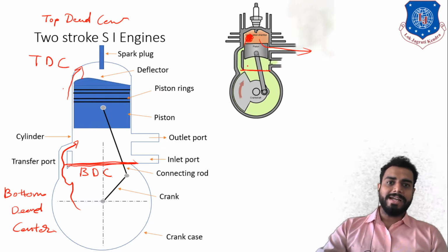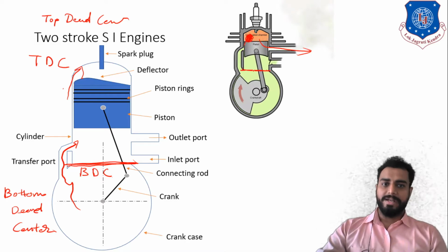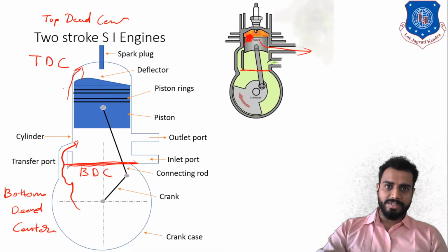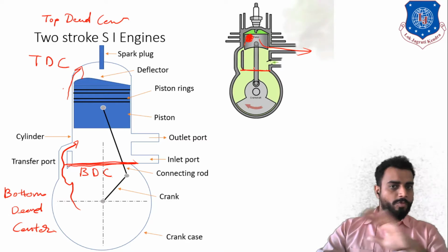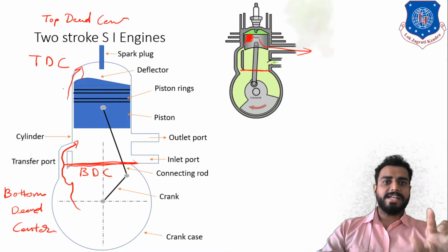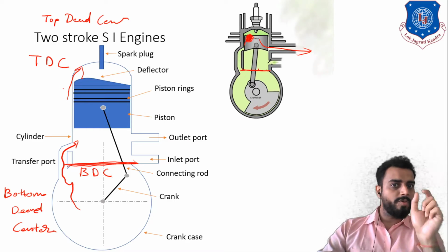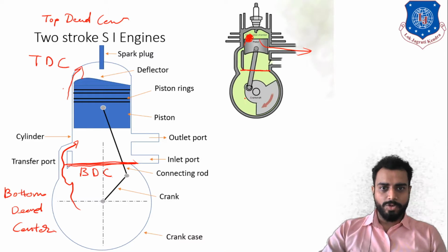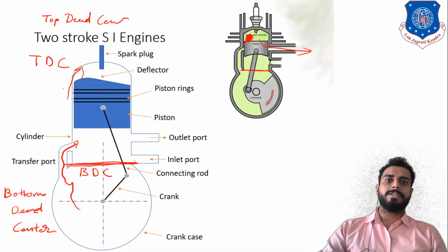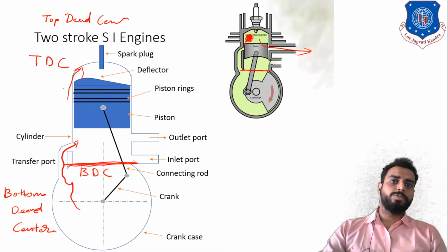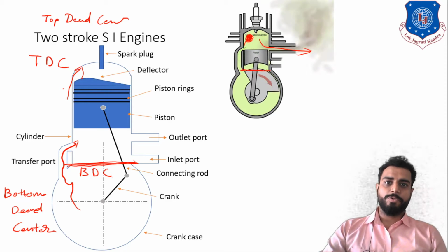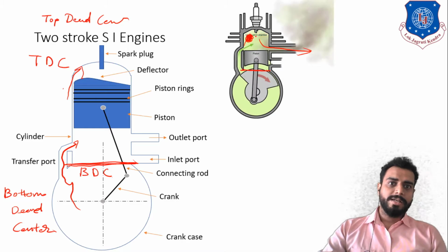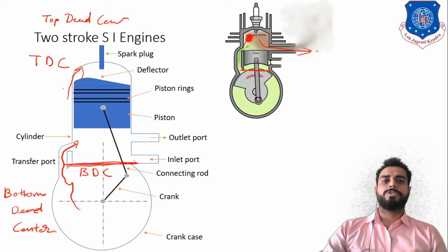Remember student, right now the piston is at bottom dead center. I hope you understood this. First of all, the piston is at bottom dead center. I am not moving it at all. At that instant, what will happen? Fresh charge which is present over here will try to transfer through the transfer port to the top side of the piston, that is cylinder cavity, and due to that, whatever amount of combustion products is already present over here will be pushed out through the exhaust port.